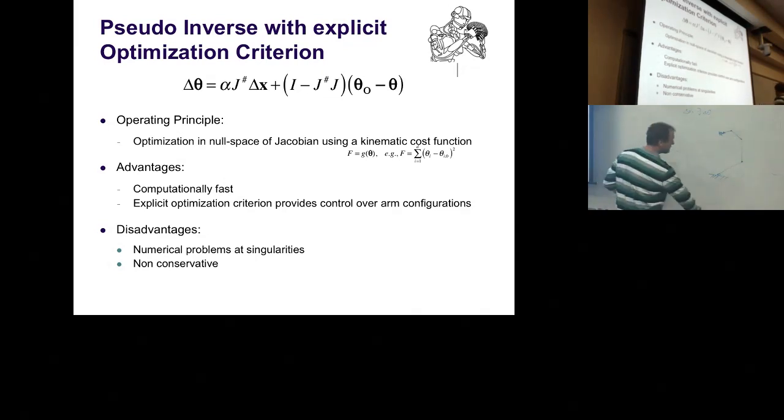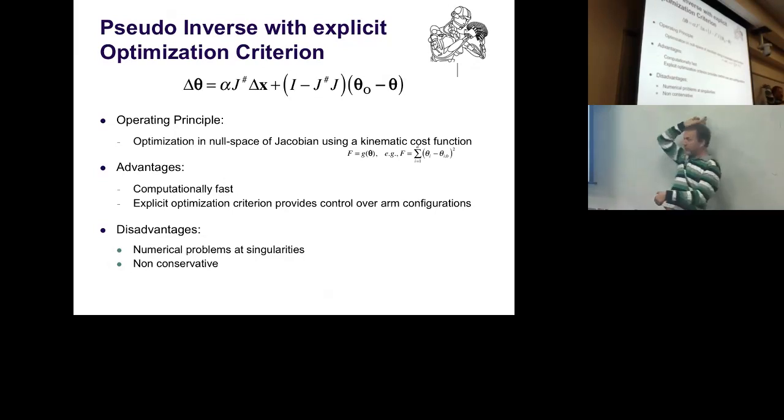So what this says intuitively is this little song and dance which I showed you before. I'm here, okay? I want to reach to this point, but my range space is realizing this point. But now I have this big null space in which I can move and do all kinds of little things. If I can express this null space algebraically, then I can make sure that any motion I'm doing can only happen in the null space, by projecting the motion I want to do onto the null space, making sure it's not in the range space. Weird language, huh? Really annoying.